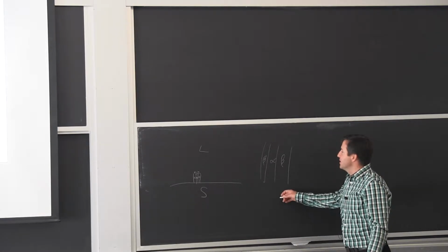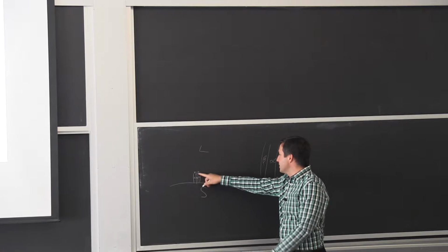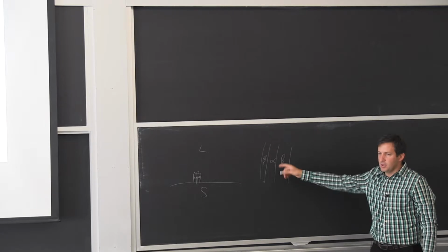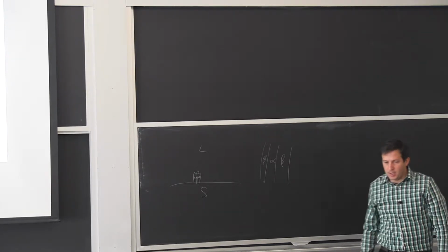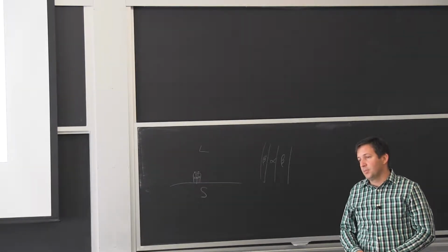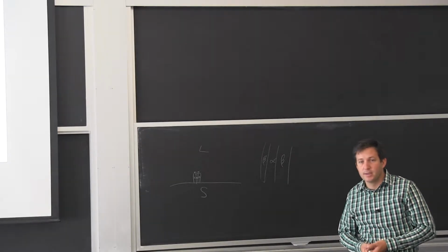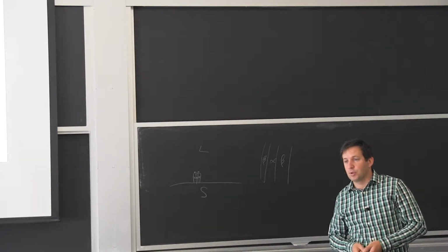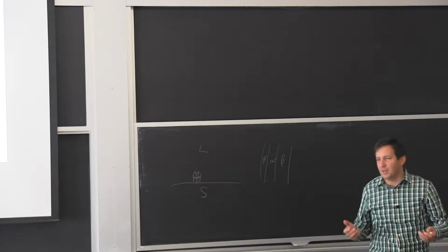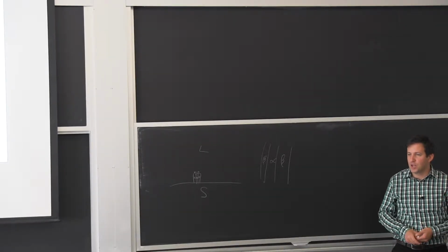But for now, let's just think relatively simply that we have a liquid, we have a solid. If we go really fast, this movement here can't go really far, but if we go slowly, then there's going to be more separation. And it's one other reason why we use aluminum silicon, because as cast, they have a relatively fine microstructure. It's still not super ductile, but it is a fine microstructure with a relatively high strength, as compared to if you cast pure aluminum, which is really soft and difficult to shape and do anything to.